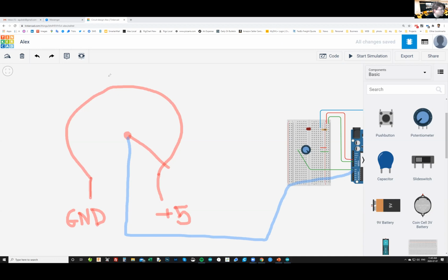If I take my potentiometer and I spin it, like 1,000? All the way to the 1,000? Well, it is correct and incorrect. Actually, it's going to be 5 volts still, but how the Arduino works with analog things, it actually digitizes it into a discrete value. So it goes from 0 to 1,000 plus something.